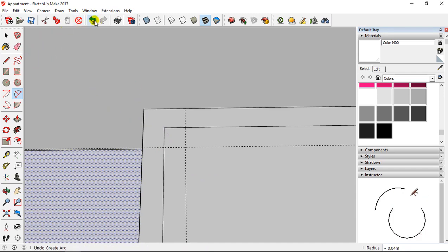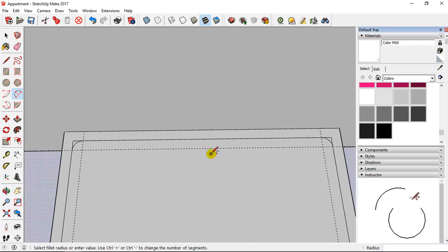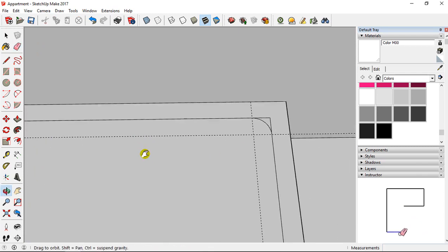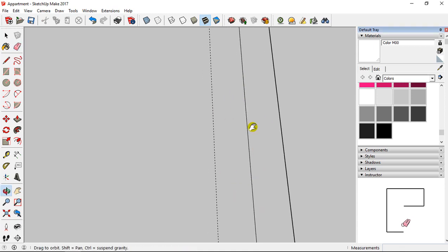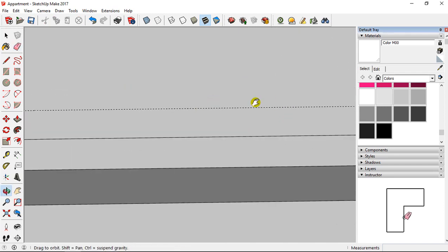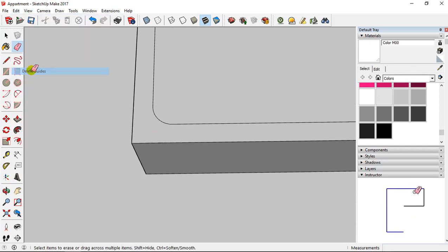Or not like this, I'm going to come back. So this point, and you need to select tangent to edge. Like this. Then after I take the eraser tool, I'm going to erase this part. I'm going also to erase this part. I'm going to go at this level and to erase this part, and also on the left to erase this part. Edit, delete guides.